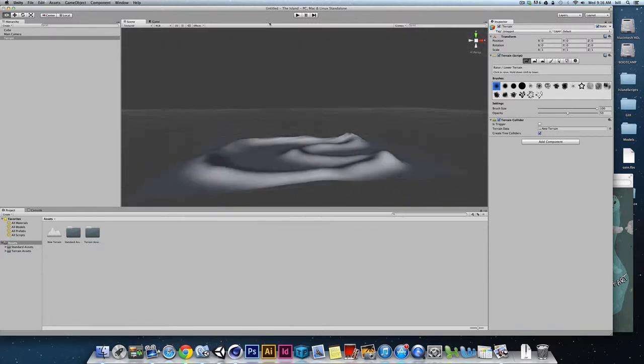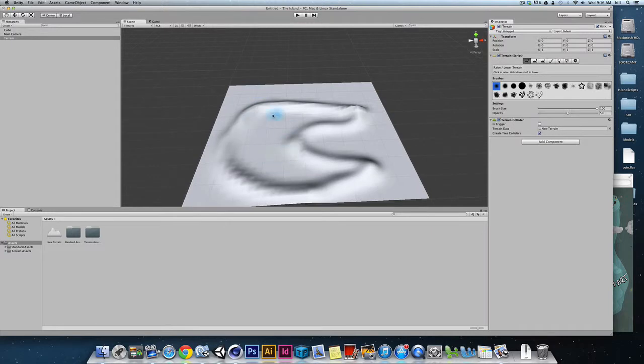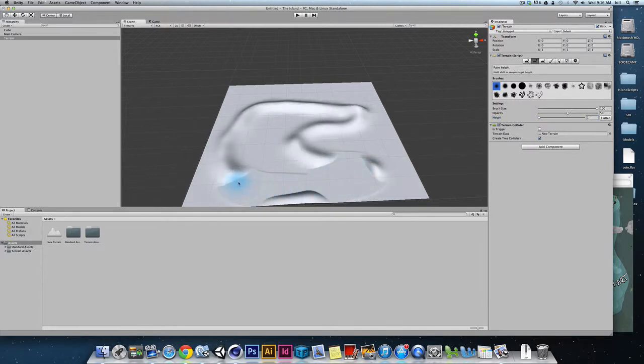Now I get the feeling that I pushed that up way too high. So my opacity was probably too high. And this is where the paint height tool comes in. So we have the raise tool and we have the paint height tool. Remember, the big difference here is that we can set that maximum height for the tool. So I'll take this back, and even for the sake of just establishing the basic shape of the map, I'll set that to 1 meter. So now when I paint this, I'm painting that map just 1 meter above what will ultimately be sea level.